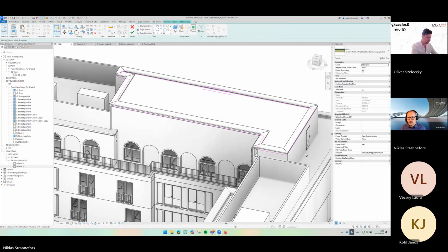I said this would be the facade, 5 meters from here. All you need to do right now is do an offset with a copy, 5 meters, and select the line that you want to offset. Because we know, if we pretend this is the facade, 5 meters, draw a line, and then all that we need to do is just trim around that and delete everything over here.